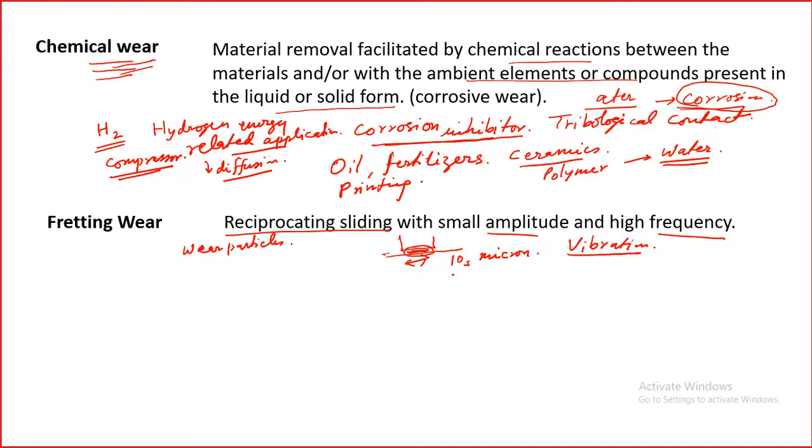Often these wear particles are oxides, and these oxides are hard and therefore very abrasive in nature. Hardness is very high, and therefore they are very abrasive in nature. So this is the sequence of events that will take place in fretting, and it's basically third body wear.